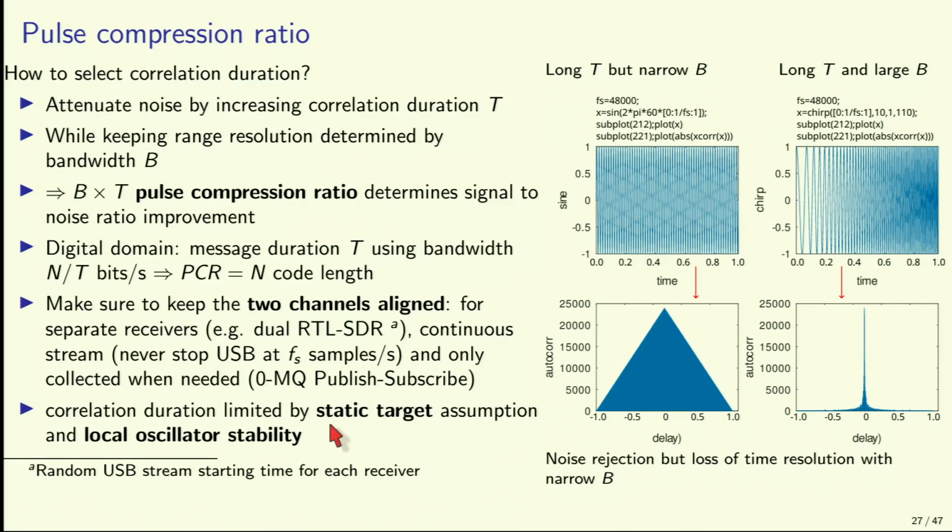If you just run a sliding average, good, you can remove the noise, but you also spread the information. You lose time information, but our radar system wants to have a sharp localization. So what you want is to maximize the bandwidth. At the same time, you're maximizing the time over which you're running the average.